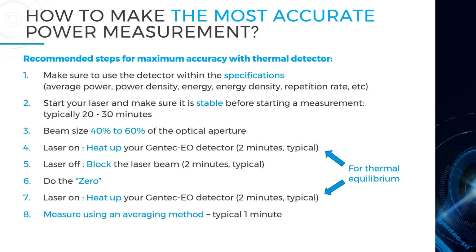So that was for Thermopile detectors. With photodetectors, it is not necessary to do the thermal equilibrium steps, but still it is very important to do the 0 to remove stray light noise. Let's have a try with real detectors.